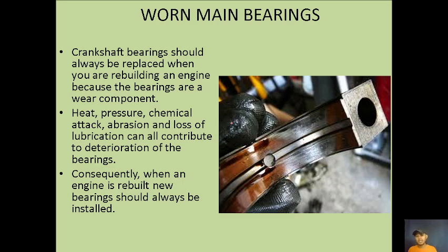So worn main bearings look like this. The first and second layer is now not good, and the bronze-type color is shown. Crankshaft bearings should always be replaced when you are rebuilding an engine because bearings are a wear component. Heat, pressure, chemical attack, abrasion, and loss of lubrication can all contribute to deterioration of the bearings. Consequently, when an engine is rebuilt, new bearings should always be installed.